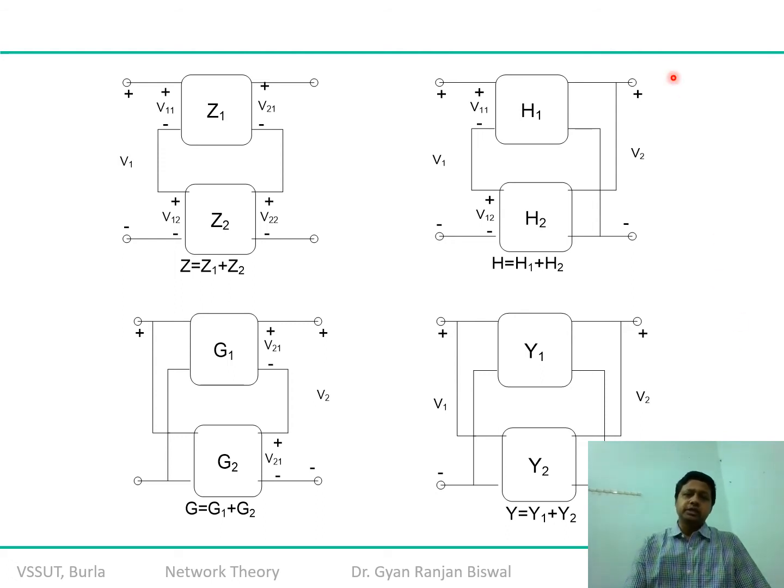Similarly, you will appreciate the serial case. On this input side it is the voltage input, and on this side it is the current. Here the parallel mode is available at port 2, while port 1 is connected in serial mode. So this is a serial to parallel interconnection. G is a parallel to serial interconnection, the reverse of the H parameter. I hope you appreciate it.